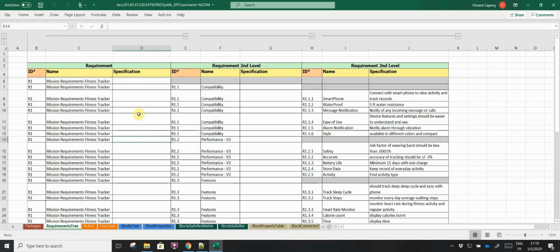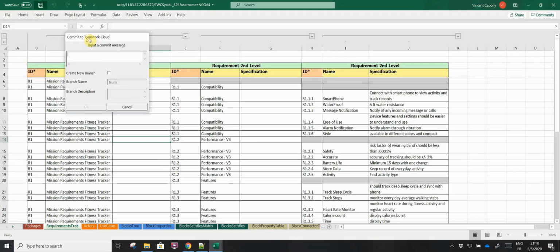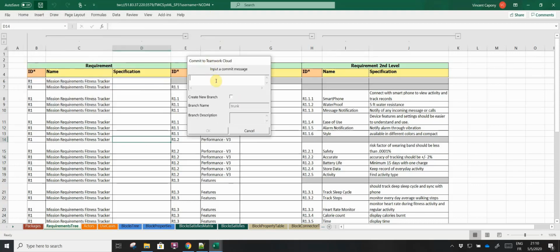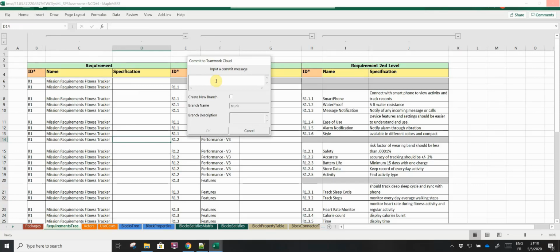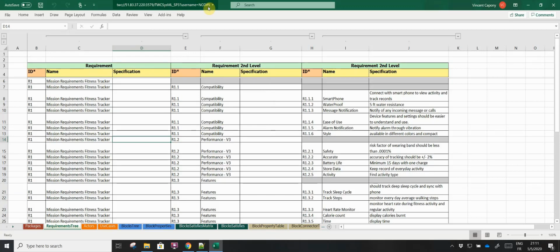For that, I double click on the save button, and while double clicking, it opened a commit window. Here I write down the comment for that version evolution, and I will be in a position to push everything down to the server. As you can see, I can even play with branches. I will not play with that today. So I click OK, and this will push to the server, and it increased the version to version 5. Okay, the modifications are now